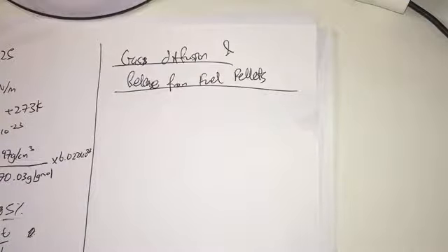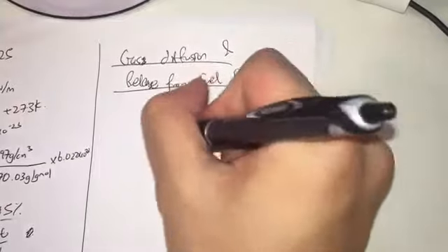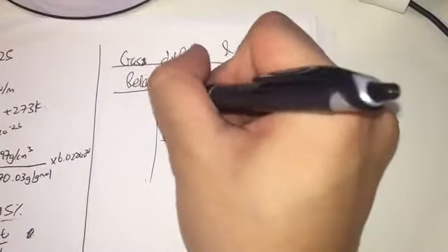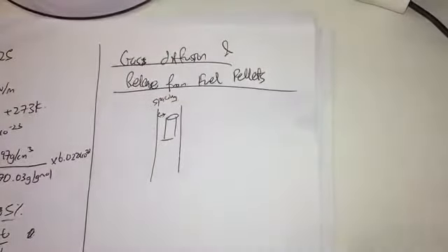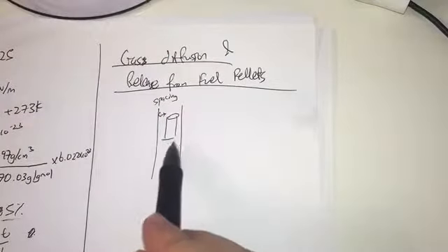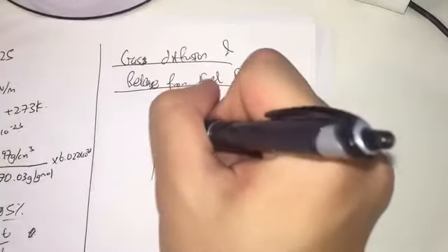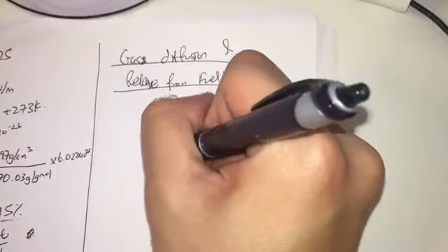Now this is great for designing a fuel pellet, because you want to see how much spacing you need to give the fuel pellet to expand while it's in the cladding. However, does all xenon get trapped like we assume? Does it all go into growing bubbles, or will it be trapped in the fuel matrix? What usually happens? Sometimes the gas will diffuse outside the fuel pellet.